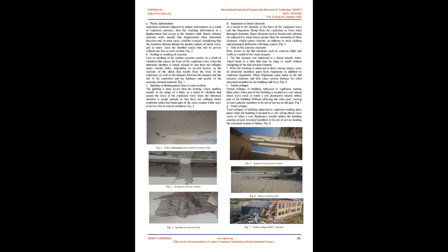In addition, there are other factors that affect the extent of damage created by explosion. 4. Structural system of building and members measurements. 5. Distance between explosion location and building, and location of explosion, air or ground explosion. 6. Explosion source and type, shell, fragment, or explosive charge. 7. Detonation general location, presence of dampers or nearby structures that help mitigate the shock.